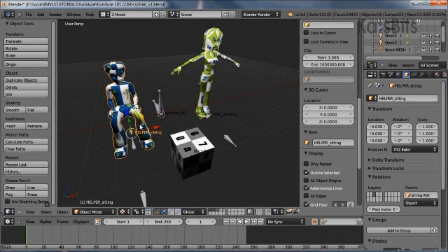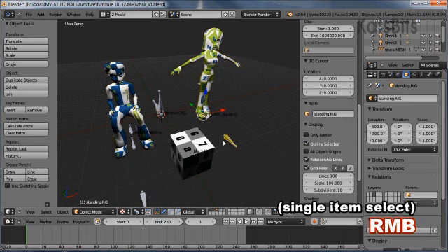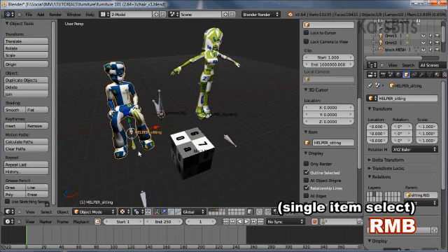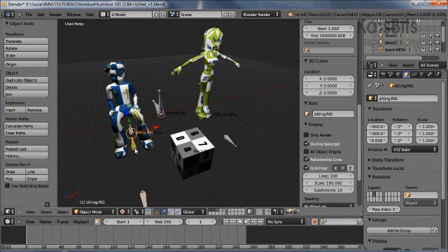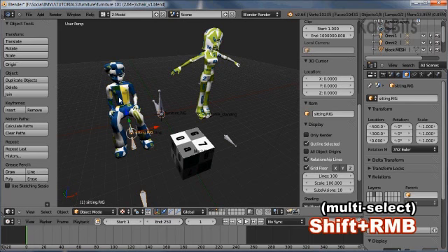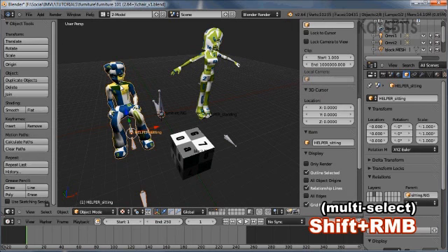So how do we do that? How do we move objects around in Blender? Well, first we select them using the right mouse button. And what we want to do is select two objects, which is the seated avatar armature, which are these grey things, and the mesh itself. So we need to hold the shift key down, right mouse click the armature, shift, right mouse click the avatar.